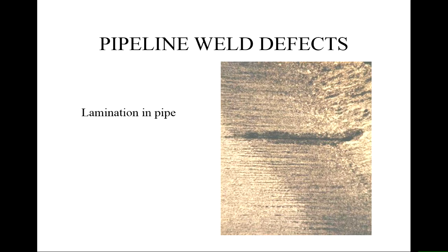Well, however, it might be. We have a lot of manganese in these steels, so it is very likely that this is manganese sulfide, which is very soft compared to other phases present in steel. And during rolling, it forms these stringers. I think that's how we called them in previous lectures. That's okay. It's present there.